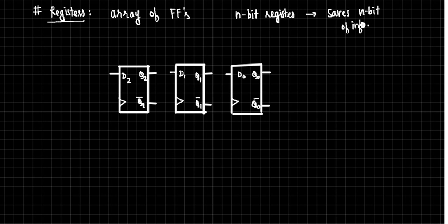They are defined as this is regarding the feeding in of the circuit, right? Feeding out can again be, we can receive or read the data again in 2 ways, either in the serial fashion or in the parallel fashion. Both are important. There are several applications where we may need serial input, serial output. We may need serial input, parallel output. We may need parallel input, serial output, and we may need parallel input, parallel output. That's how these registers are defined. So these registers are classified as serial input, serial output, serial input, parallel output, parallel in, serial out, and parallel in, parallel out, PIPO.